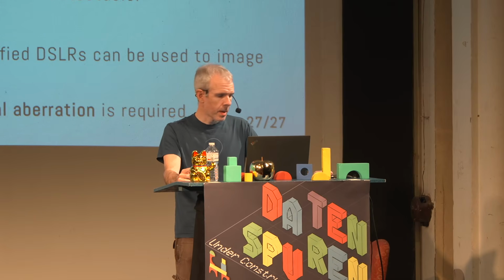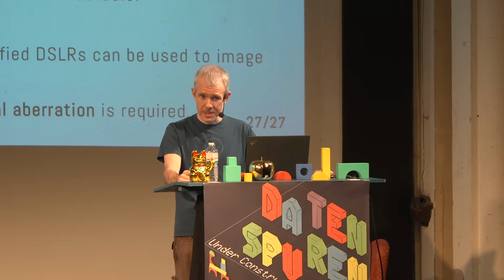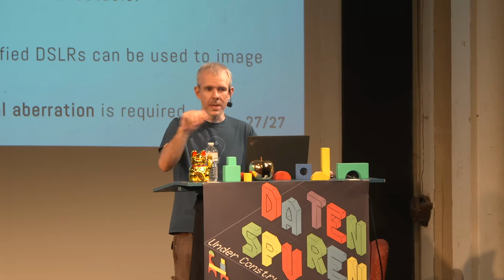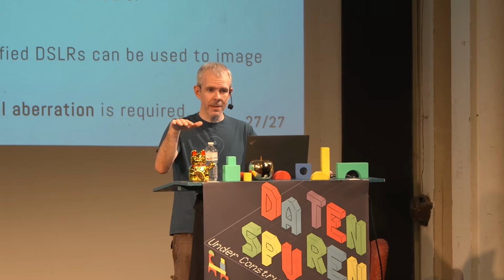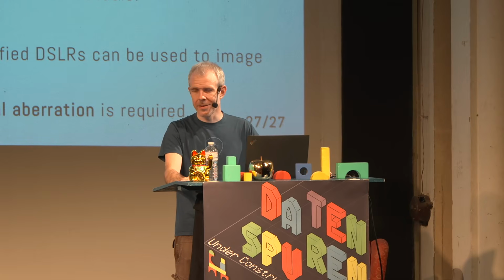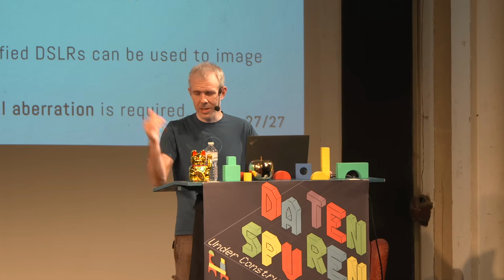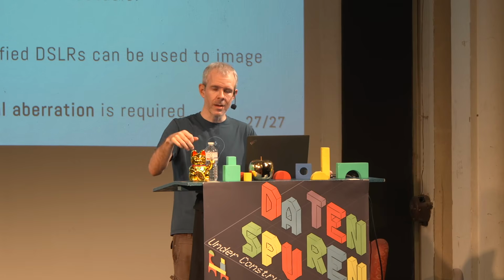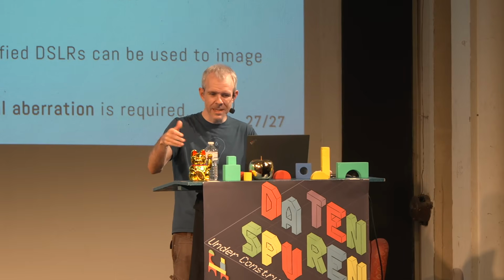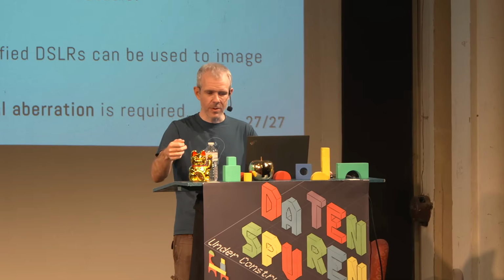With these kinds of chips, there are actually 2 problems that I noticed. One is that if you have a BGA, typically they sometimes have a standard PCB at the bottom layer. When you want to dissolve it, it's also epoxy with fiberglass. It's really nasty, and especially if you want to do it with hot air, you have this small PCB piece in the chip, and it's quite bad to get the epoxy off correctly.